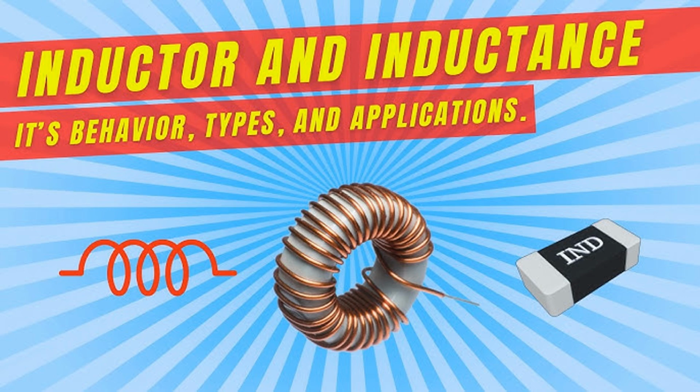Applications of current limiting with inductors. Inrush current limiting. Application: inductors are used to limit inrush current when electrical devices are first powered on. Inrush current can damage components or trip circuit breakers if not controlled. Inductors help reduce the peak current when the device is switched on by opposing the sudden influx of current. Example: in power supplies, inductors limit the inrush current when the supply is first connected to the power source, protecting components like transformers and capacitors.